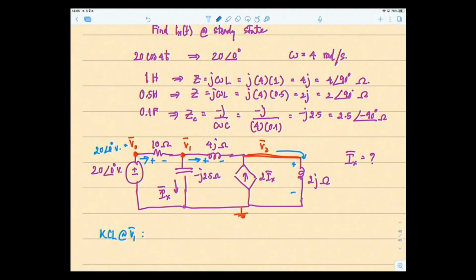Right, Kirchhoff's current law. I'm going to change it right away into the node voltage form. So this is the current going in. The current is the voltage drop across the 10 ohms divided by the 10 ohms. The voltage drop across this 10 ohm is the potential difference between the positive terminal at this point, minus the potential on the negative terminal right here, on this side.